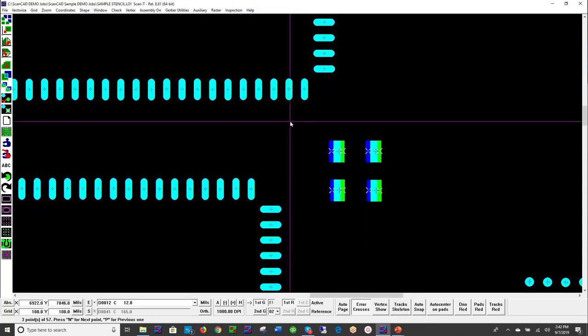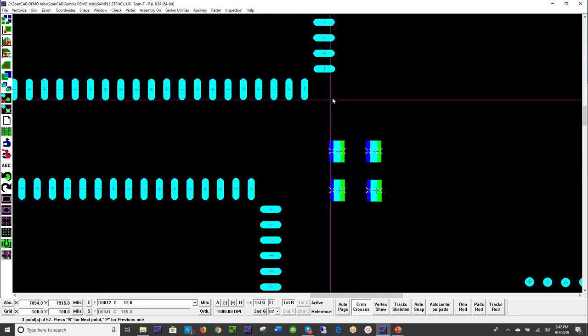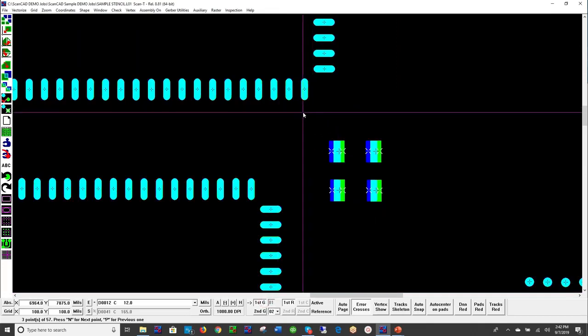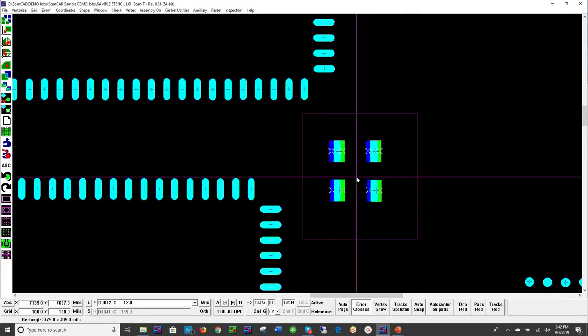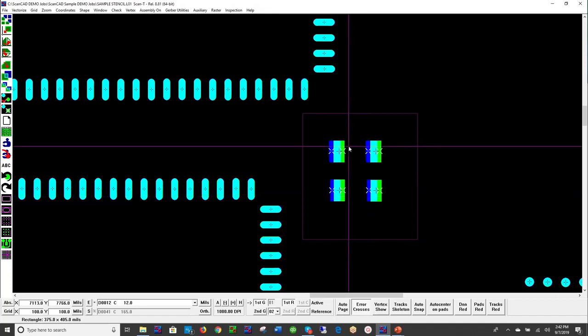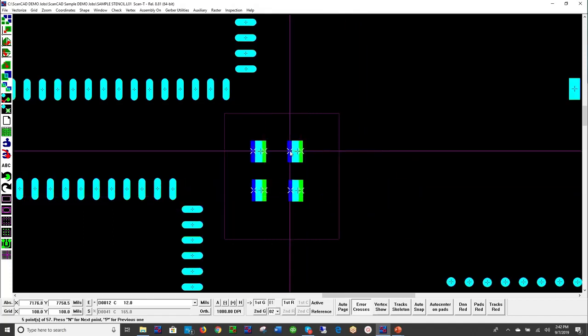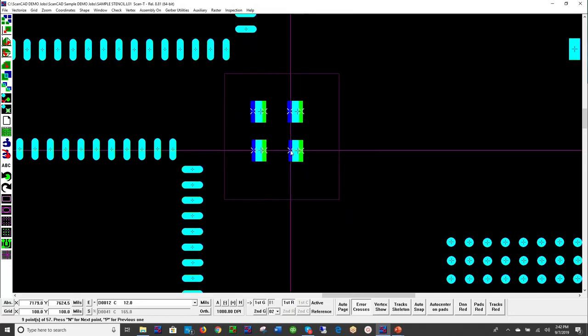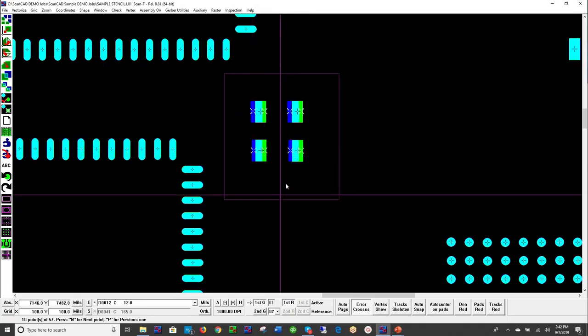The next error is an alignment error. This is an example of a possible revision change, because you can see that the other features are aligned beautifully, but for some reason, these openings are not in the right position. They're shifted to the right. So indeed, that would be a serious manufacturing problem. I'll skip through this. This is now error number 10.